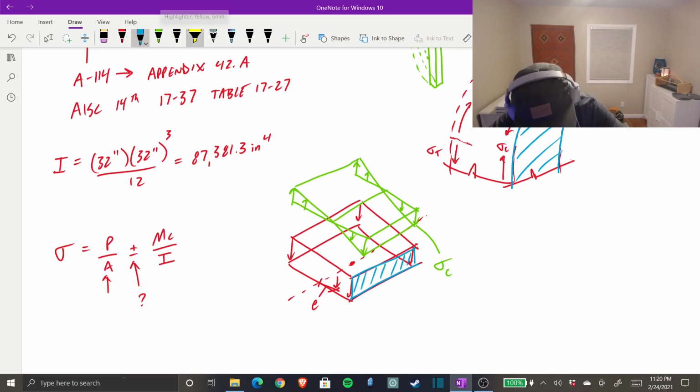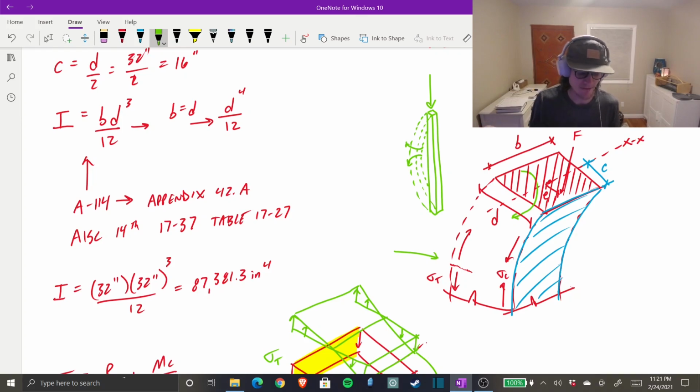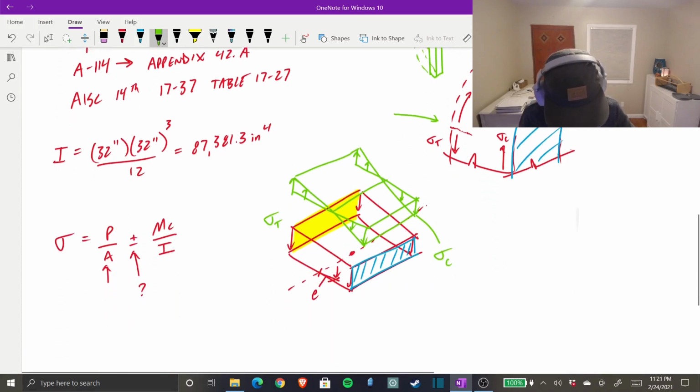But then, I draw in yellow, on the other side, that back face, you're introducing tensile stresses on that side, because as we talked about right here, if it were to be concrete, if enough bending stress was introduced into the column, you'd actually have cracking on that far face because you have too much tensile stress building up on that extreme fiber.